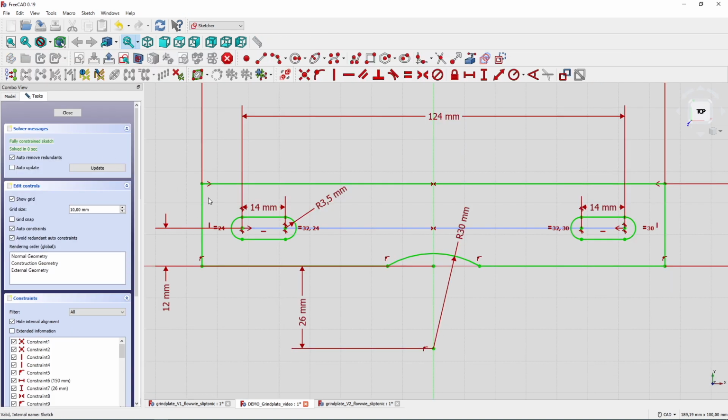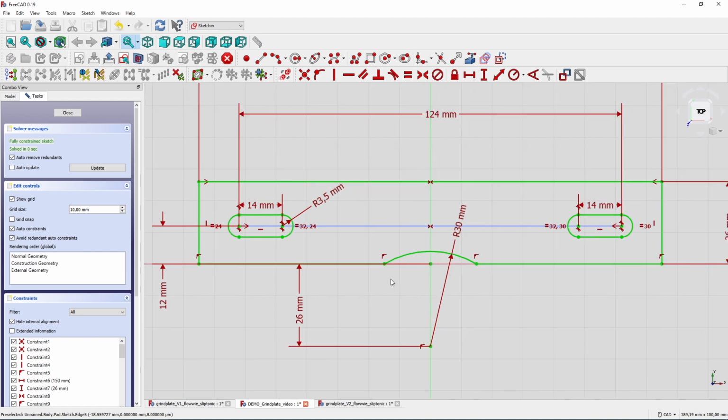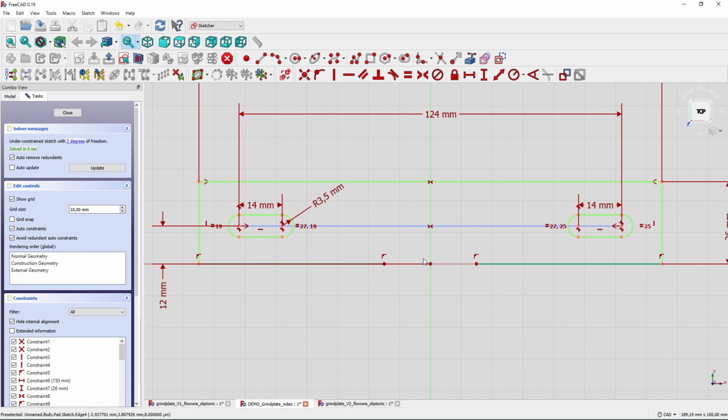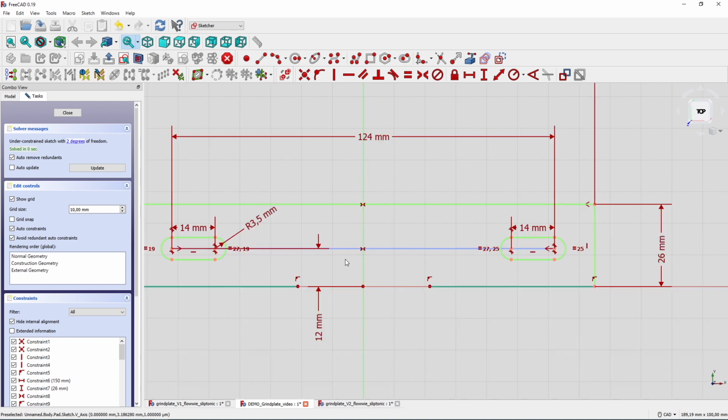When I go to basic shape sketch, I will now delete completely the whole radius down here. This could cause some errors. Let's find out what happens. Nothing so far. That's pretty good. I have now these 2 points down here. I will add an 18 millimeter radius here and make the transition from this edge and this edge into this radius less sharp and filleted.